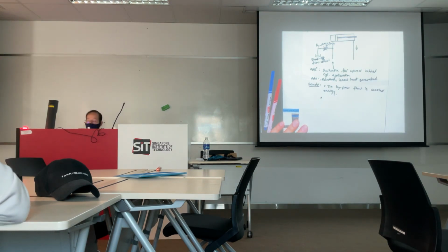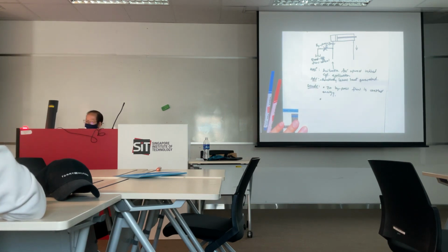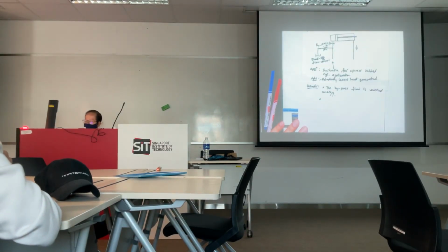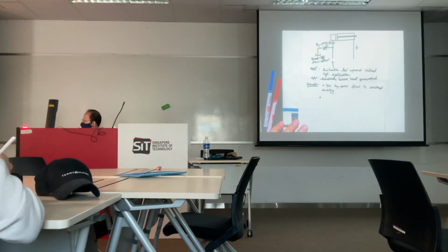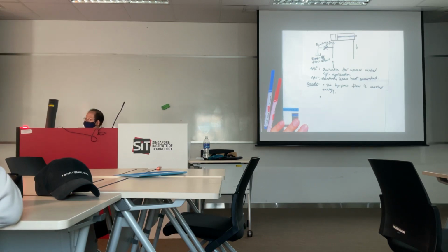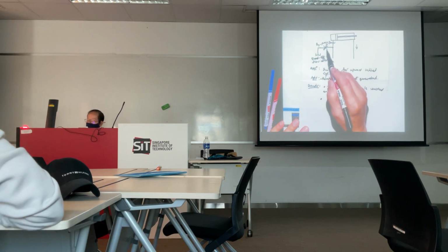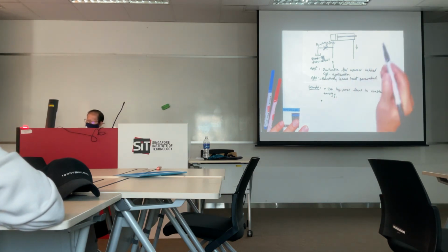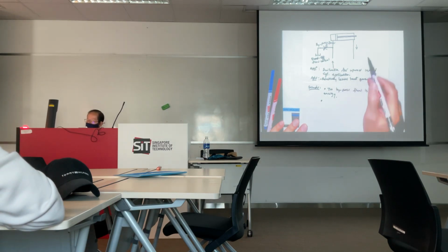Can you have one here and another one connected to the same pump? You think it's possible? Cannot, isn't it? Because if you adjust this, the flow from the pump, because the next circuit will also share the same pump, the pump flow going to the other circuit will be affected.